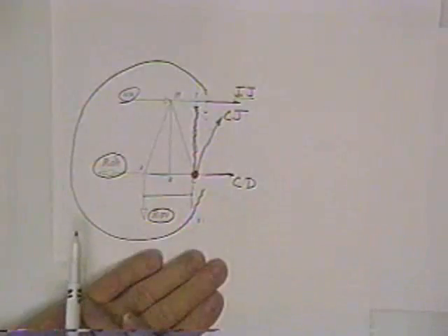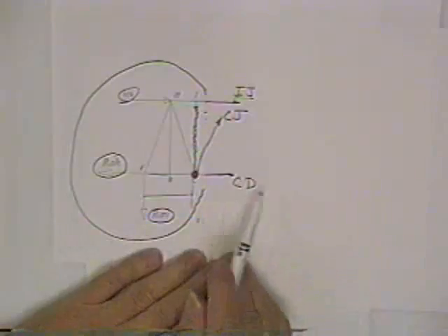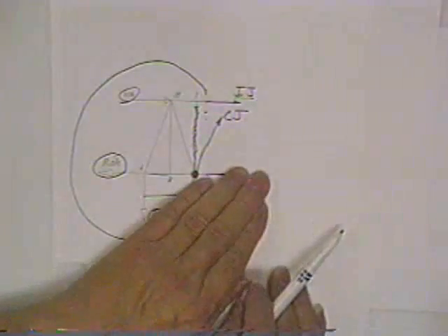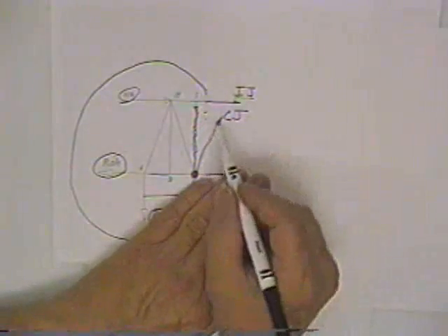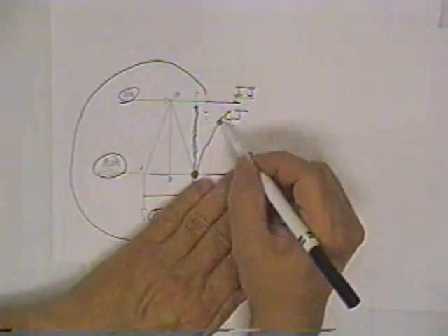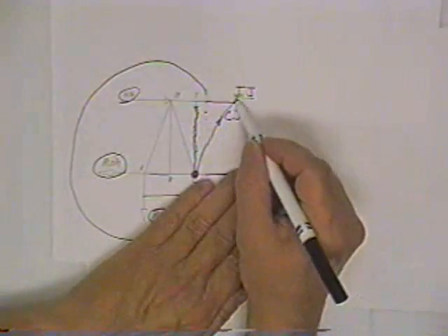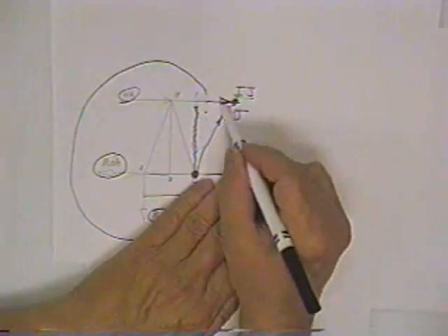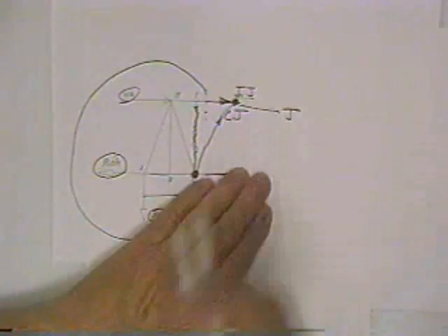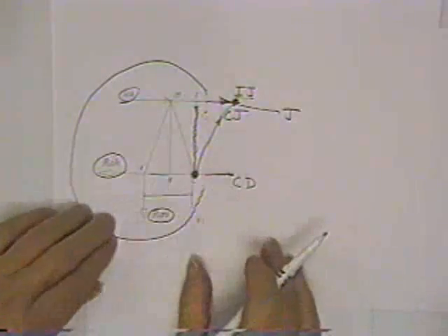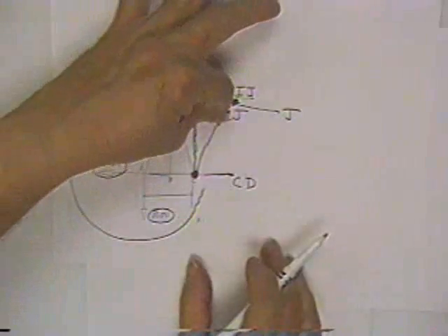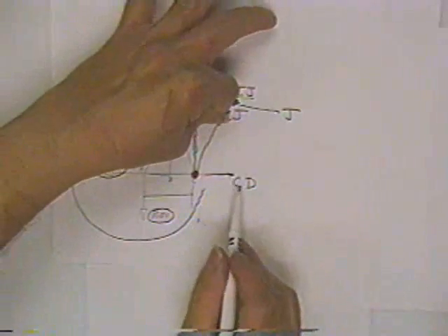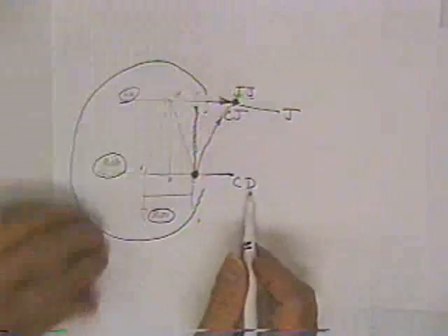I can use the same free body to solve for CD. If you want CD, cover it up. Who do you hate? I hate IJ and CJ. Follow them until they meet at a point. They meet at point J. Sum moments about point J and they will drop out of the equations. You can immediately pick up and get CD.